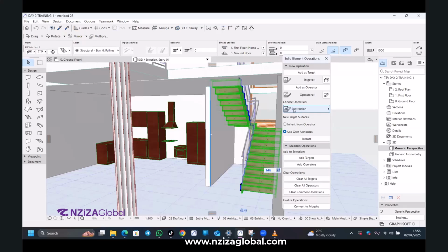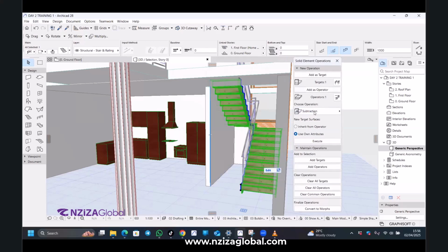It doesn't come. Choose subtraction with downward extrusion. Just the way, the third one from the top. Already done that. So already selected it. Subtraction with the downward extrusion. Then click execute.